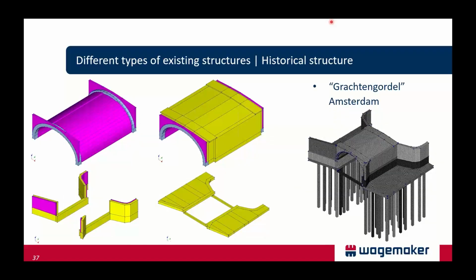So we made a three-dimensional finite element model in Diana, as shown in the figures on the left. The model consists of several different segments, different parts. And the final mesh again looks like the figure on the right-hand side. In this model, we used solid elements to simulate the true behavior of the bridge deck, which in fact is rather stocky, right?